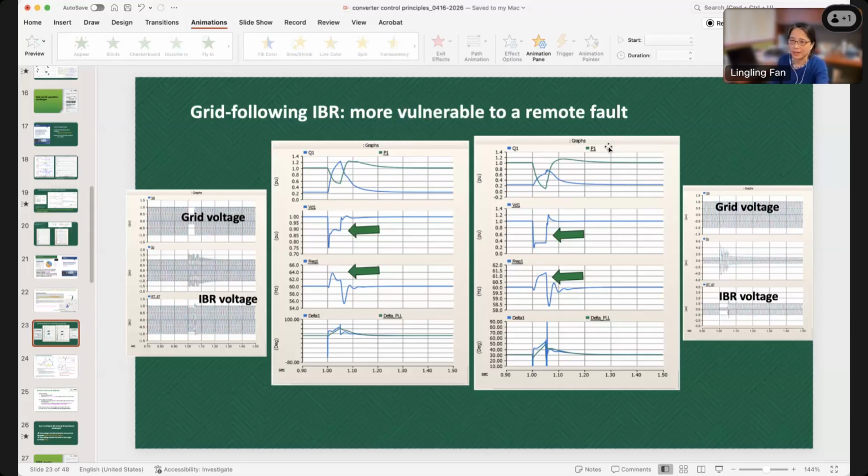It's just which one you put into the grid that's cheapest. When you have lots and lots of inverters, some of the batteries you want to design this way. But again, with lots of solar PV, you don't change it because maybe the original design is good for them. You just need to add a couple of batteries to do grid forming. Yes. Let's go to the next question, if we have time.